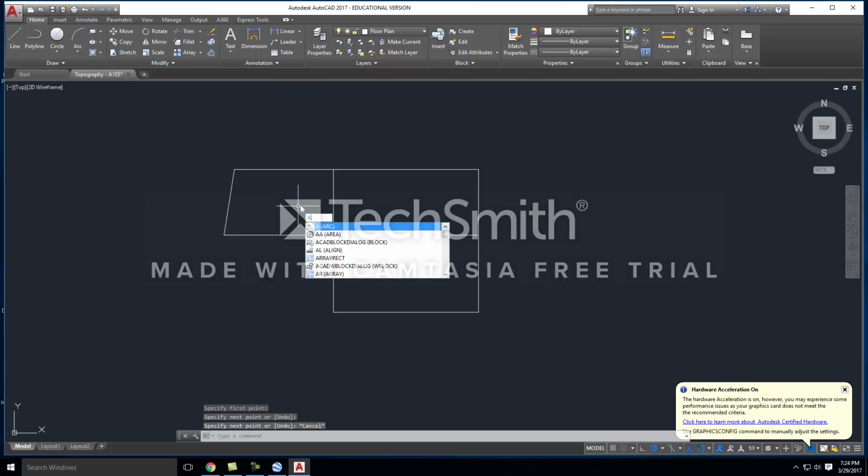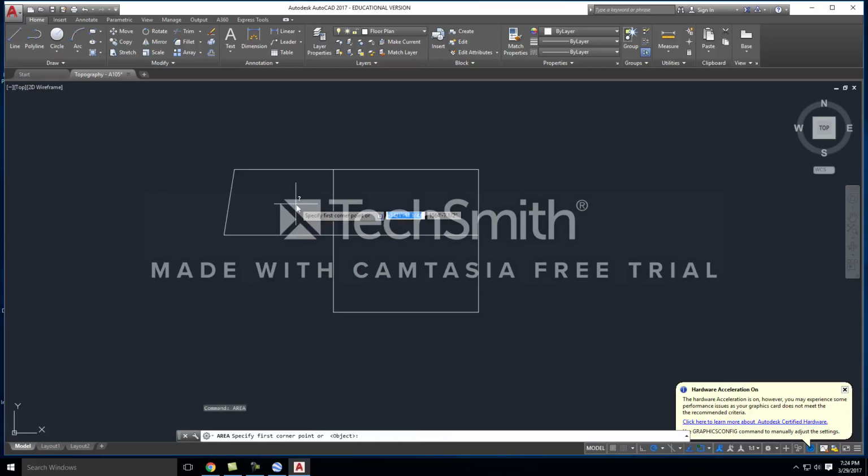If you type in AA, that's going to be the shortcut for area. You can also just type in area. What it's going to tell you to do is specify the first corner of the area that you're trying to calculate. So if I click on the first corner, we'll say it's this one right here.